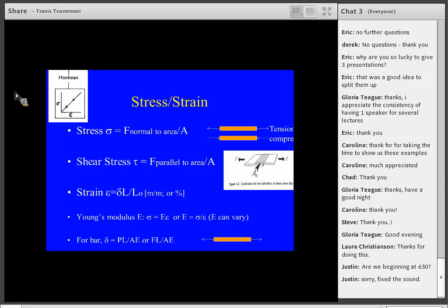And normal stress at the top there is simply the force normal to the area. Shear stress is where you are shearing something, so it is the force parallel to the area divided by the area that is in shear. It's a slightly different variation, but still it is force per area is stress. And typically it is still linear with the strain that's being applied, the stretch, the deformation. And at least for some reasonable distance, these are linear. They will stretch, and then they will return to a less stretched formation.